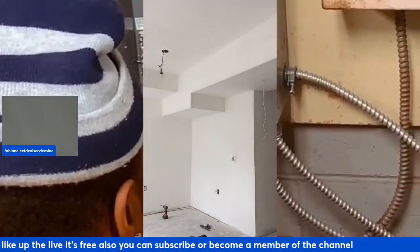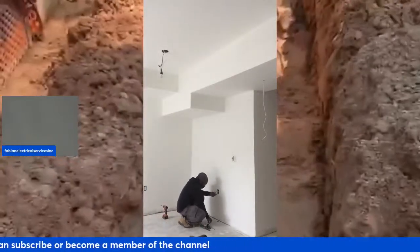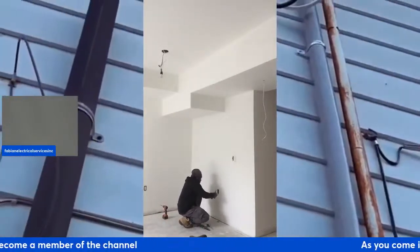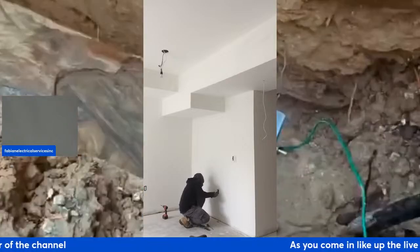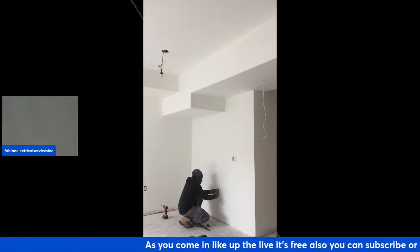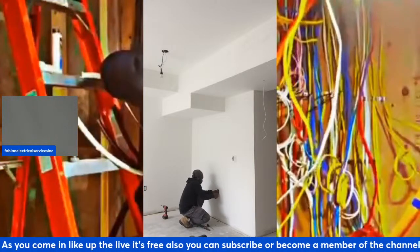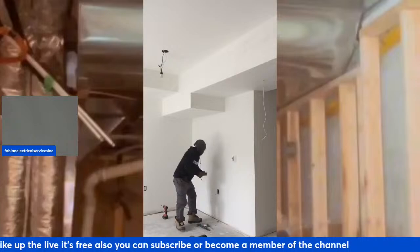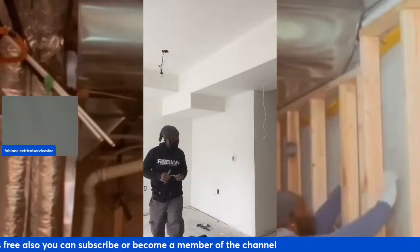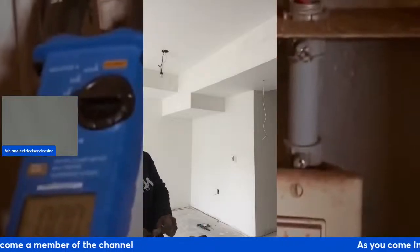Also, a lot of times people will install the receptacles, but they will not take into account the TV itself. Most of the time, it's better to have the TV on its own, but if it's not on its own, you can, as long as you have that whole circuit with an arc fault.